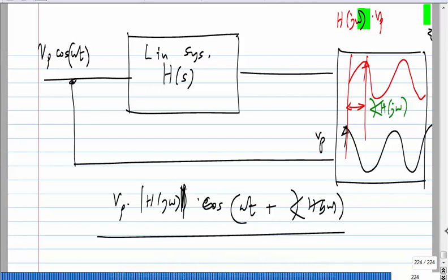Is this okay? And you combine this with any signal can be represented as a sum of sinusoids. So you can find the response to any signal now. A square wave also you can find. What you have to do is take harmonic by harmonic. A symmetrical square wave has the fundamental and odd harmonics.